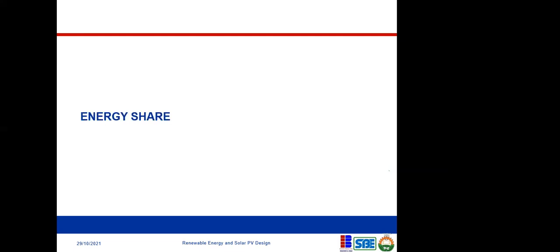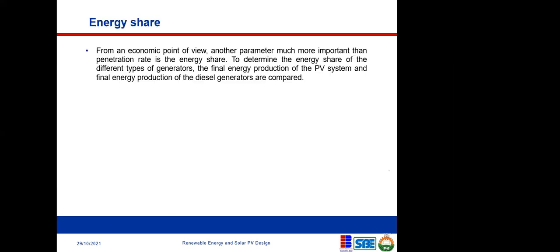So let's talk about energy share. I introduced this earlier when I talked about penetration rate. Penetration rate has to do with power, whereas energy share has to do with energy. From an economic point of view, another parameter much more important than penetration rate is the energy share. To determine the energy share of the different types of generators, the final energy production of the PV system and the final energy production of the diesel generators are compared.